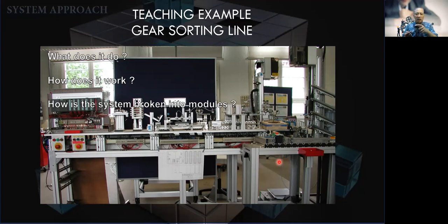You can check the connection, the module, the battery modules. It could be the battery modules. But when you check the battery, oh, this is working. Or maybe it's the ignition, maybe the combustion, whatever it may be. If it is an electric vehicle, maybe the motor doesn't work. Maybe you're using a battery and then you have the inverter to start the motor, because it's three-phase, so you have to convert from DC to AC. Maybe the inverter. So when it is modularized, we know where to check.